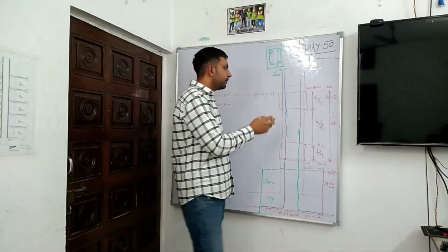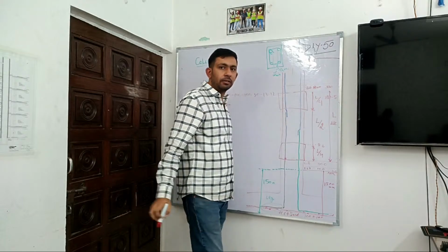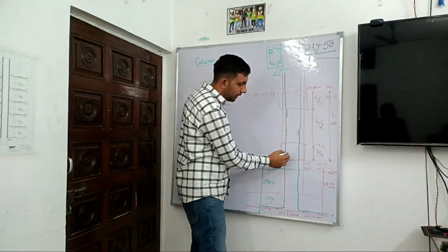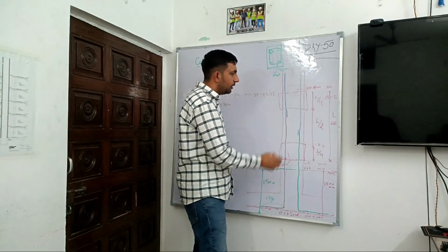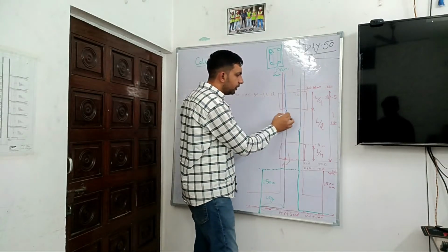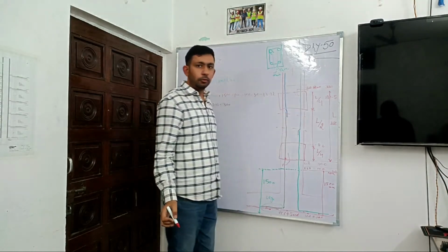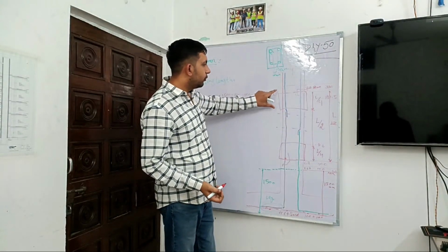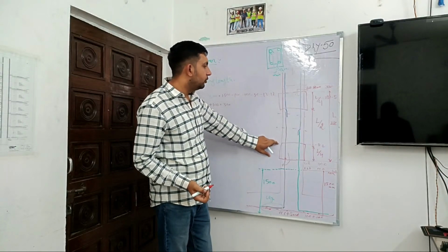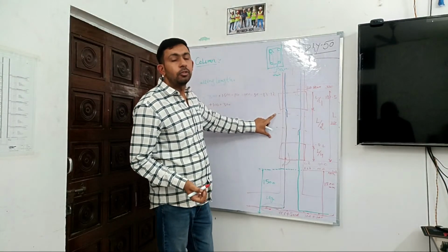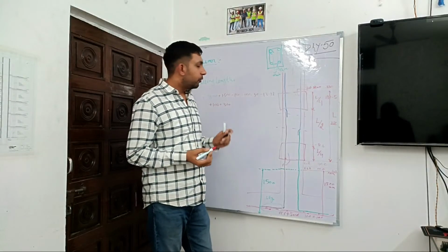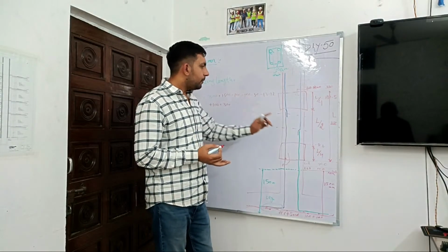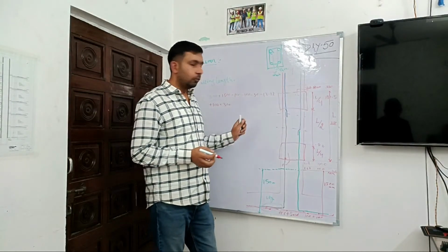It means maximum stress is there and load transfer also takes place there, because from slabs load comes to them and from here this goes down this way. The remaining portion is our non-confining zone. I hope it is clear to you all that this L by 4 portion and this L by 4 portion is the confining zone and this L by 2 portion is the non-confining zone. So, while providing reinforcement, we will provide our lap joints in the non-confining zone. So, it must be clear.